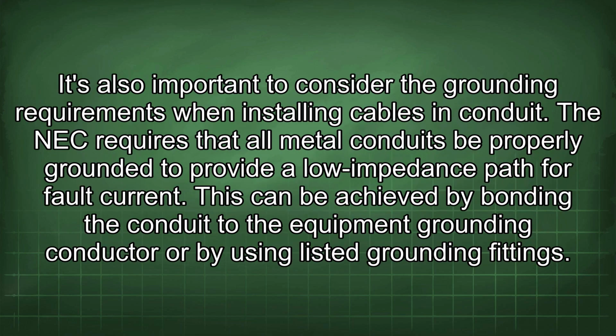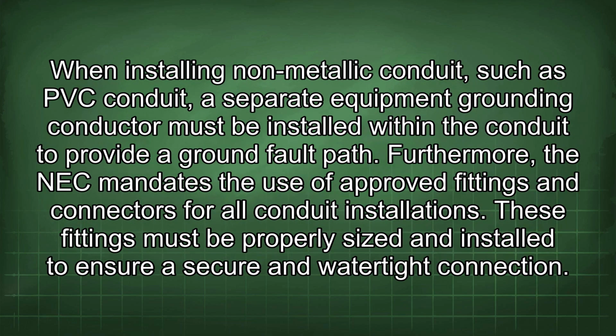It's also important to consider the grounding requirements when installing cables and conduit. The NEC requires that all metal conduits be properly grounded to provide a low impedance path for fault current. This can be achieved by bonding the conduit to the equipment grounding conductor or by using listed grounding fittings. When installing non-metallic conduit, such as PVC conduit, a separate equipment grounding conductor must be installed within the conduit to provide a ground fault path.